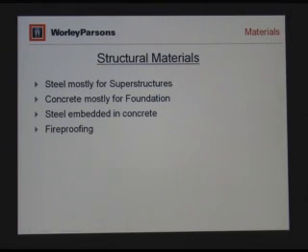Steel embedded in concrete, again, would be primarily for anchor bolts to anchor down the vertical vessel equipment. Fireproofing for steel, and one item that's not here, and we don't do much in that, is for small buildings like a substation, for example. We use masonry block. Masonry block for us is kind of an interesting design also.